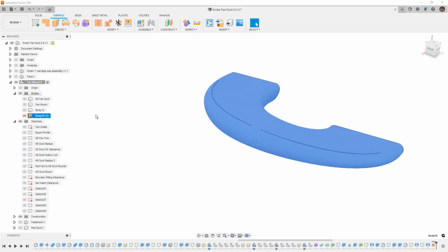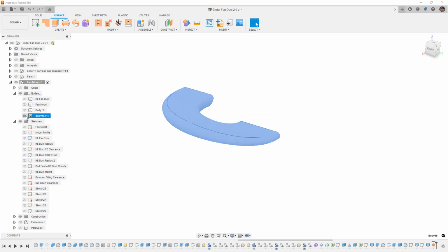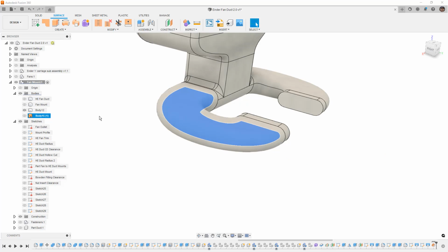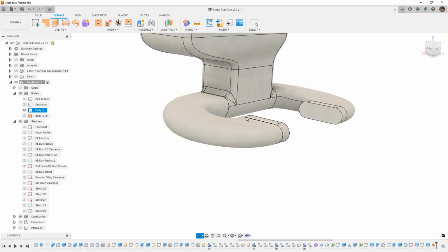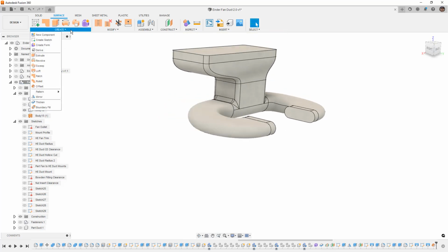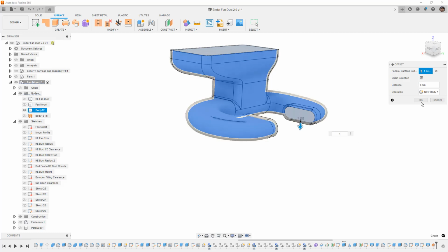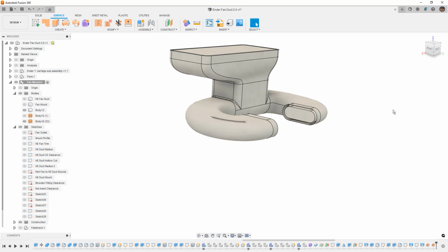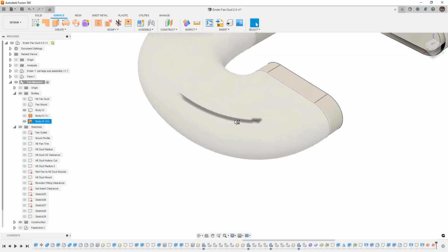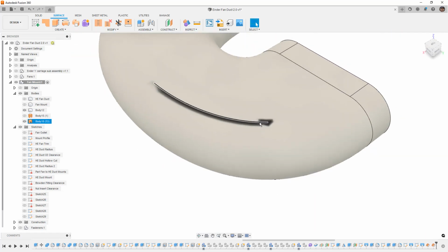Obviously, we created the offset inward, so we would be able to, say, create an offset inward of this or outward of this. So if we try to create an offset on the exterior, we're going to chain selection because we do have fillets everywhere, and try to make it 1 millimeter external. You can see that we are able to build that, even though there is a problem in this corner here.